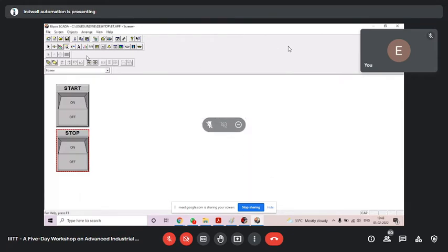You understood. For a switch, we have button in this software. In another software, the name can be different. Another, let me show you the preset value. Preset value is for changing a numerical value. This changing numerical value we can have for anything like timer, counter, temperature, pressure, for anything. So wherever or whenever you want to change a numerical value, you want a preset value. In this software, the option is set point. Set point. In HMI, it was numerical entry. Here it is set point.